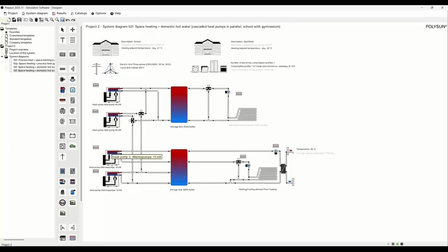And here with the 10 kilowatt heat pump, we can go to 10 out of 100 kilowatts. So that would be as much as going down to 10%. And even if you run that variably, inverter controlled, you can go even lower to, let's say, 3%, like 3 kilowatts out of that 100. So with this setup, you can control the power and cater to varying loads, and also to peaks, and also to partial loads where it becomes really effective.